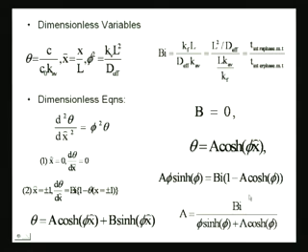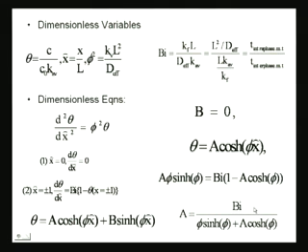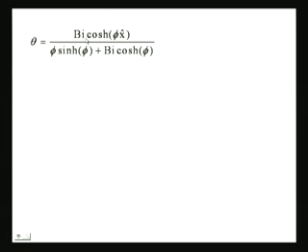So, I did this without the gamma out here, but you can just put the gamma in there and it would not make any difference to your equation. So, this would be your theta that you get at the final thing, but again without the gamma, and if you put the gamma in here, if I remember, yeah, it will come over here. The Biot number would come with a suffix of gamma. Okay. So, it will be Biot number times gamma cos hyperbolic x and this.